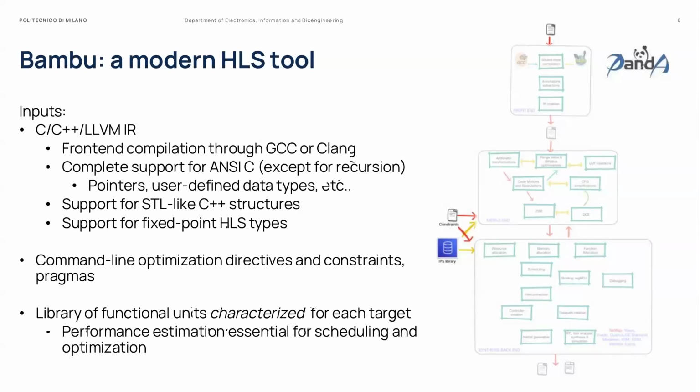If you have STL in C++, you can just replace them with the ETL, the embedded template library, that can be synthesized. And we have the support for the typical fixed point types that are used in most HLS tools. We also have some compatibility with the pragmas used in Vivado or Vitis HLS, the tool by AMD Xilinx.